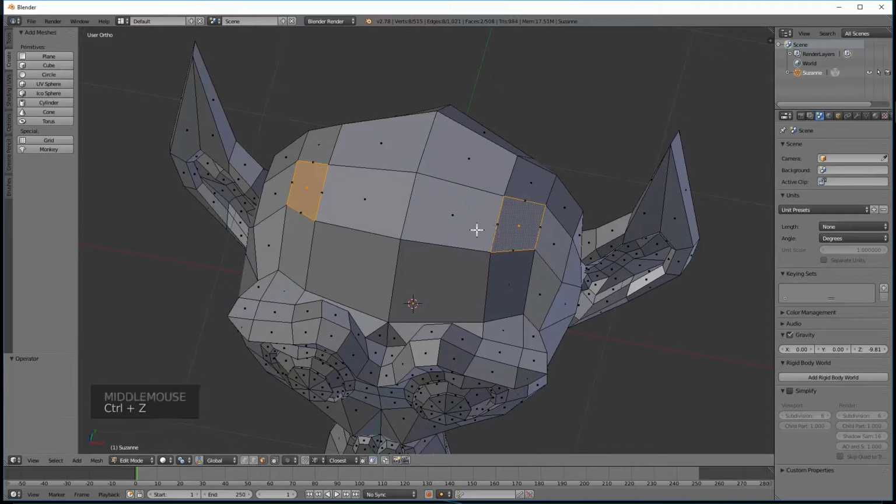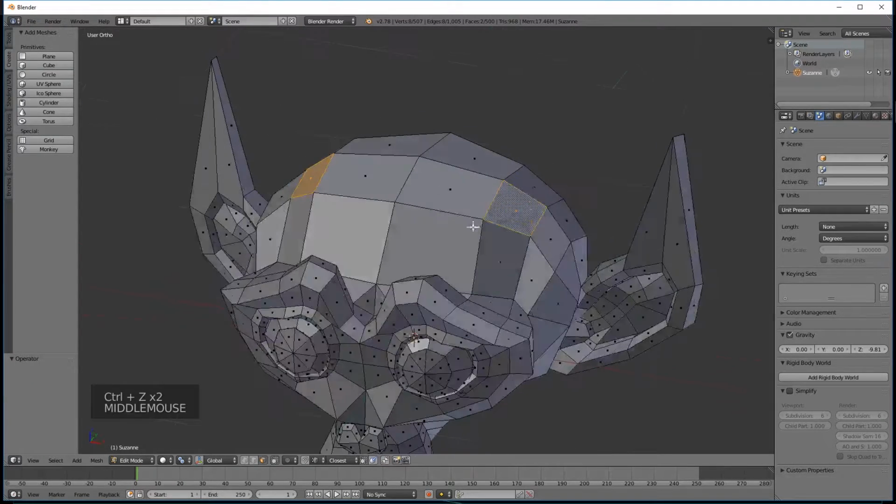Oh, see, I just made a mistake. When I extruded there, I didn't do anything, and I extruded again. You can see, watch this. Alright, and then we'll right click. See, now those little points there, there are faces there, but I didn't move this point, so that's going to cause problems for you later down the road in your models, so always make sure to undo that.